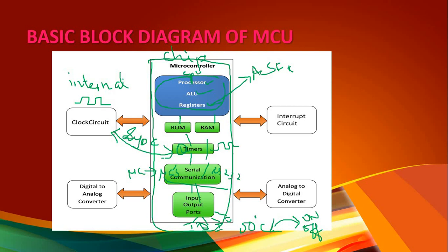That is the work of I/O ports. For the input pin, I am giving an input of 50 degrees Celsius, and once 50 degrees Celsius is reached, to an output port I have given an instruction to switch off. The output connection is the lamp. Input is the temperature setting, output is the lamp. What is the output? It is the LED glow. It may be on or off.